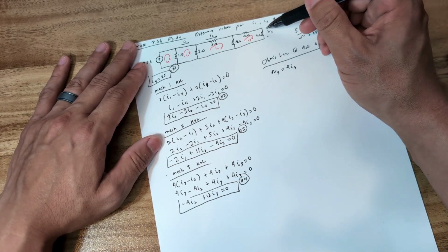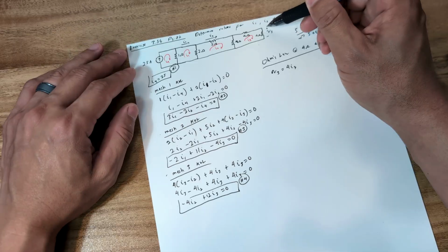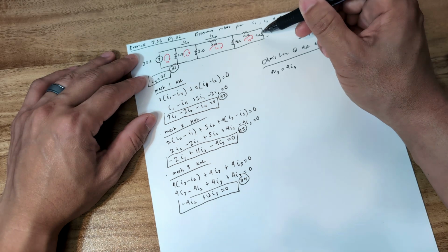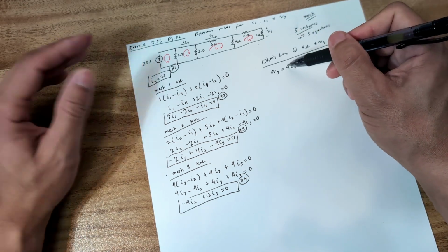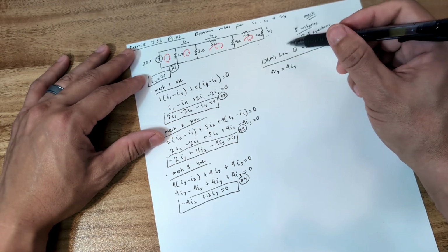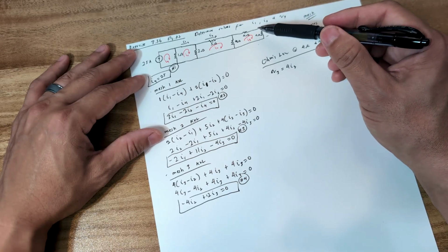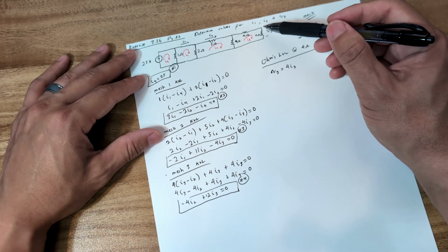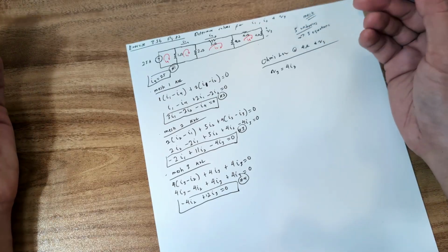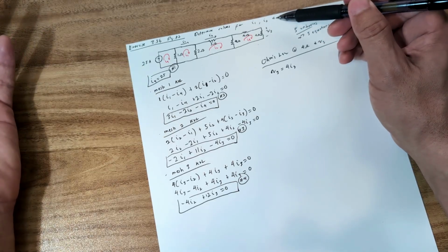But since this is entering the positive terminal of V3, this 4 ohm, you don't need to do any negative. You don't need to flip the signs. So because of passive sign convention for a resistor, the current is always going to be coming in from the positive terminal, which a resistor doesn't really have any terminal, but wherever the current is entering in, that's going to be your positive side usually.